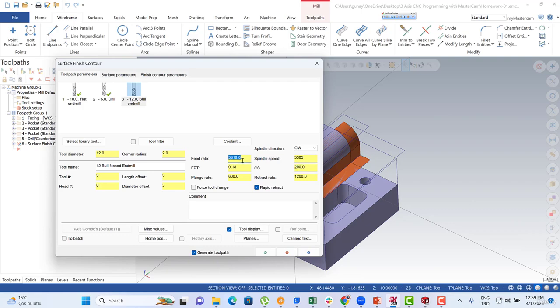It's going to be better than the previous one, but we're going to see here the tool wear, okay, is not good for us. And when we consider the tool wear, when you use the 200 cutting speed, it means that we're going to see more tool wear after that process.